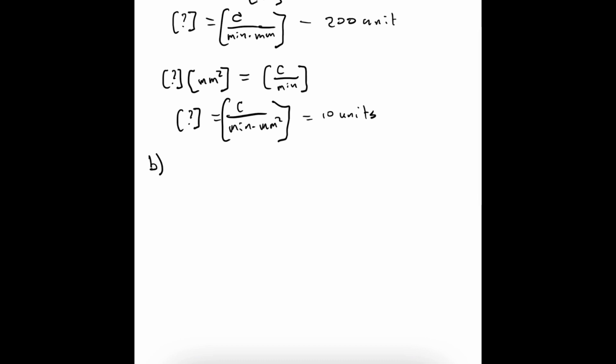For part B, we have to calculate the crystal nucleation rate in crystals per second corresponding to a crystal diameter of 0.050 inch. Now our equation is only valid for certain units. Well, now they want us to calculate what the rate is in different units using inches instead of millimeters. In order to use our equation, d has to be converted into millimeters. So they gave us d in inches. Let's convert that into millimeters.